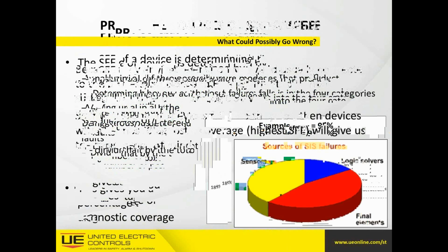Right. So it really all comes back to somebody like Exida doing a test on the product, giving you your safe failure fraction that gets you to your SIL level, right? That's 100% true. When someone comes to you with an instrument and says, as we said before, I'm SIL rated, or even SIL certified, or even SIL suitable, there has to be supporting documentation from either Exida, which is most commonly used, or TUV, which may be used by some of our European instrument manufacturers, or FM. Mostly you're going to see Exida and TUV.